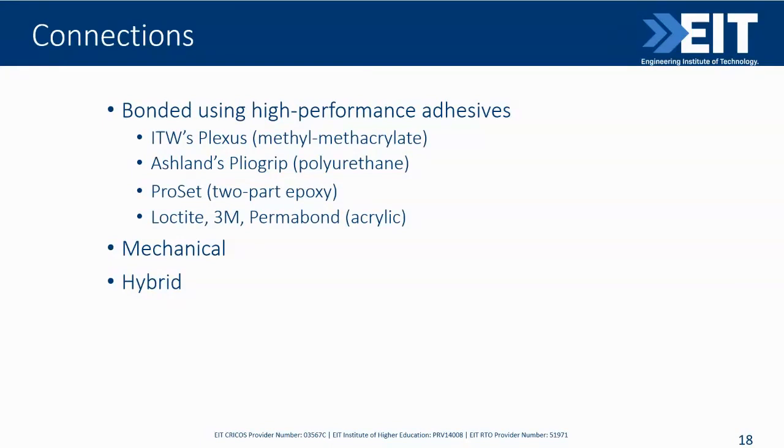So what we use instead is high performance adhesives and mechanical connection. Well, a bolted connection is also mechanical, but it's not really adequate for composites due to the high flexibility of the matrix.